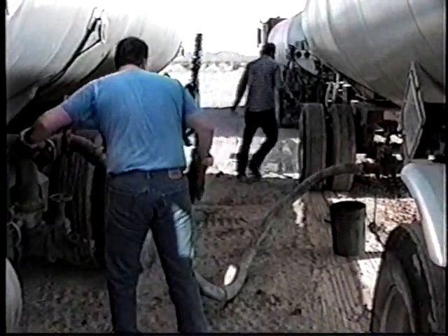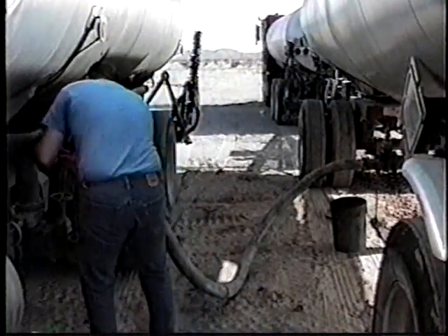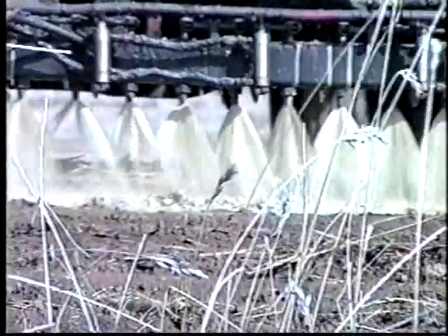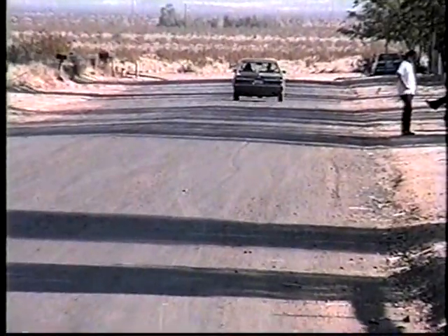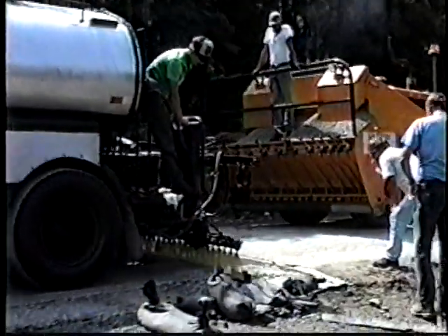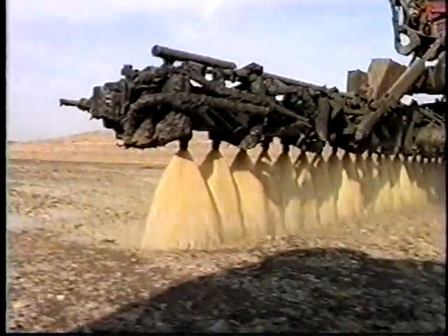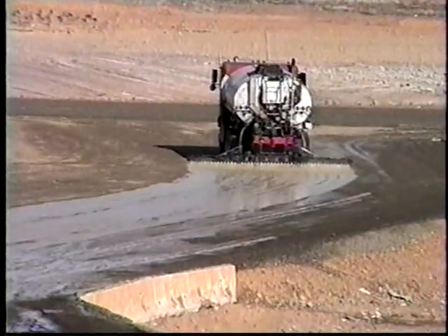Road oil can be diluted with water for applications where surface penetration is essential. Surface penetration is often the method of choice for dust control of unpaved roads, traffic surfaces, road shoulders, runways, and helipads, for erosion control for areas of bare earth and material stockpiles, and for prime coats, tack coats, fog seal, and surface seal applications.